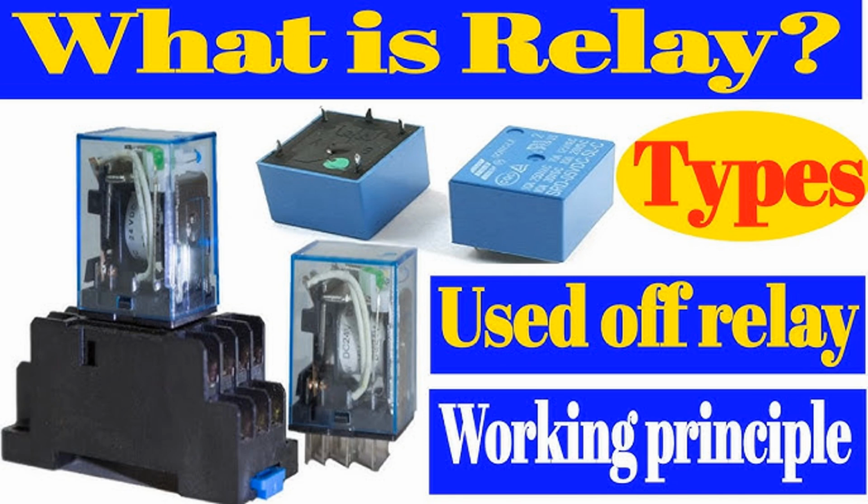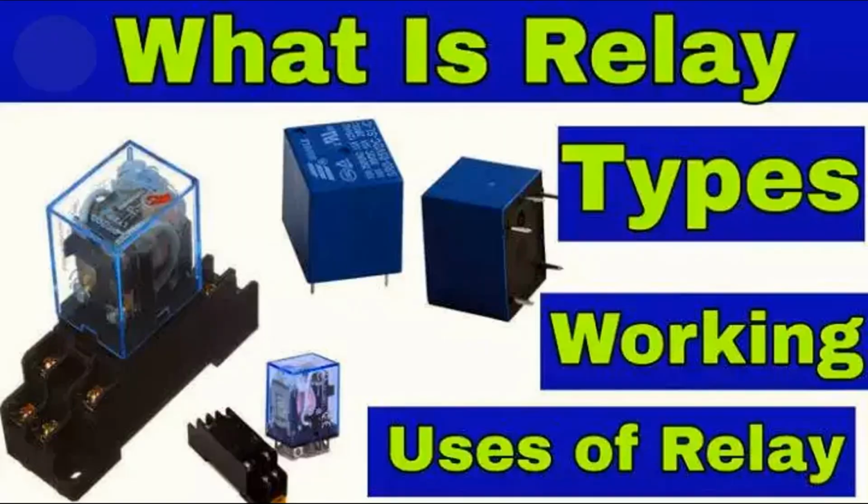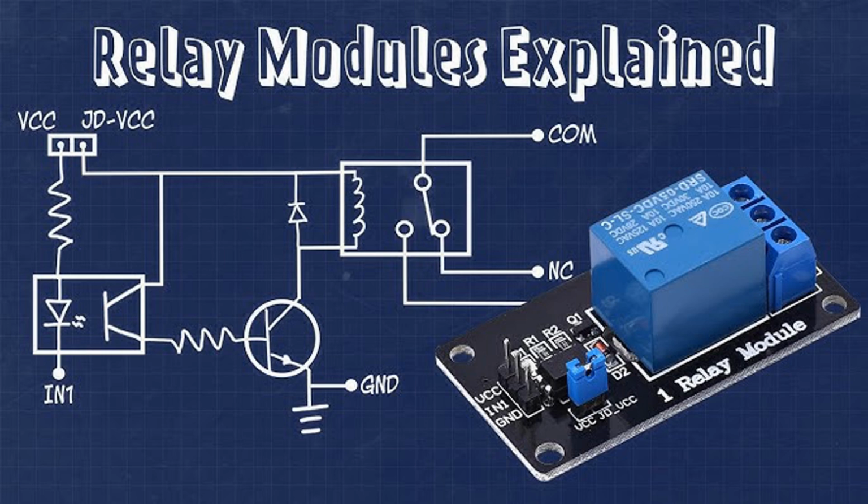Types of time delay relays. On-delay relay: the relay contacts close after the specified time delay when the control signal is applied. Off-delay relay: the relay contacts remain closed for a specified time delay after the control signal is removed. Interval delay relay: the contacts change state for a set duration after the relay is energized, then return to their original state. Programmable delay relay: offers flexibility in setting different time delays and may allow for various timing functions through digital controls.